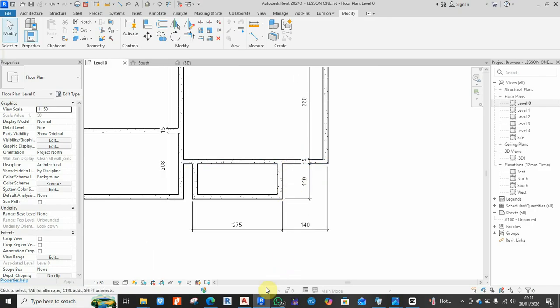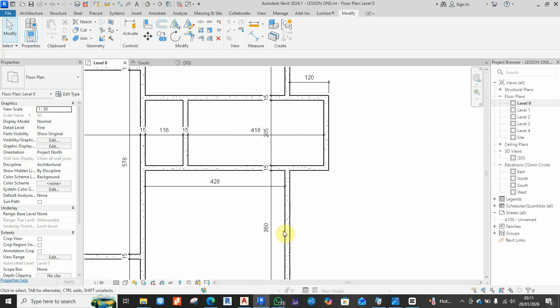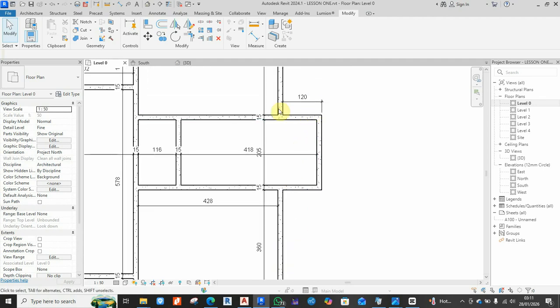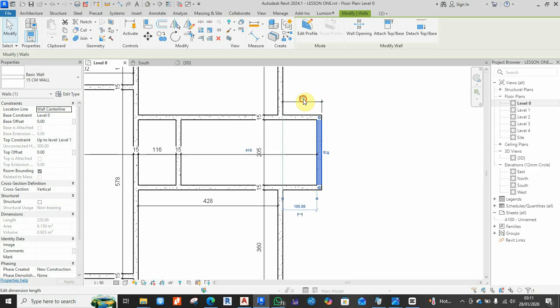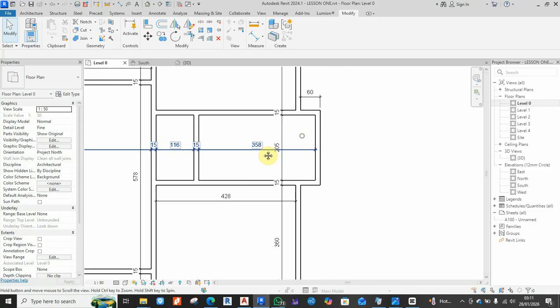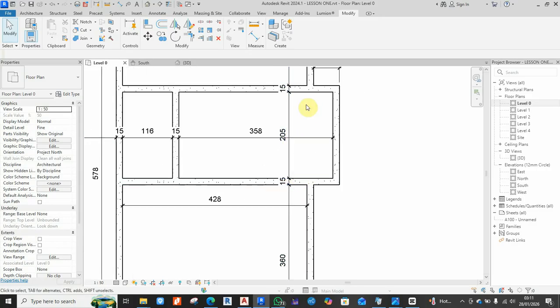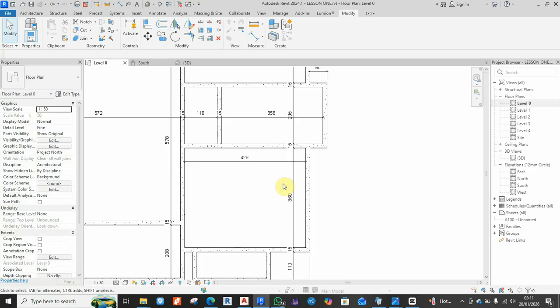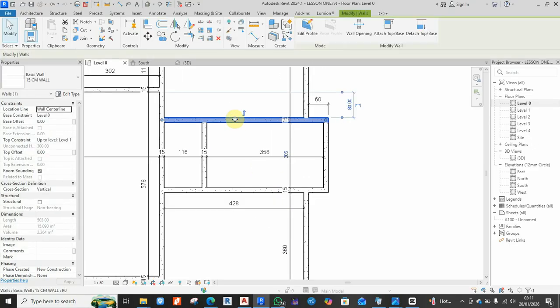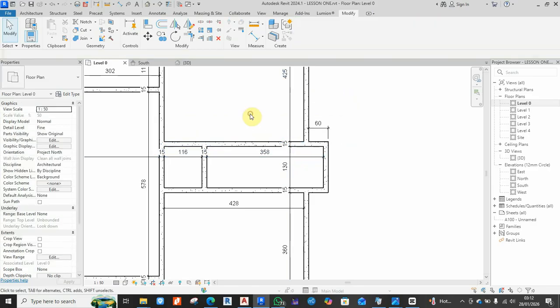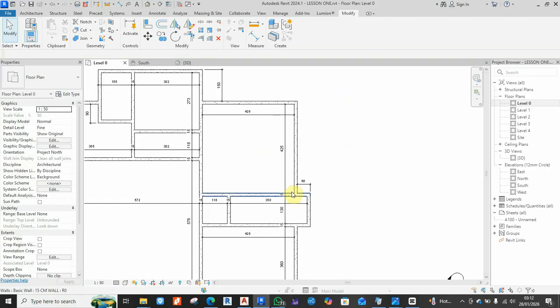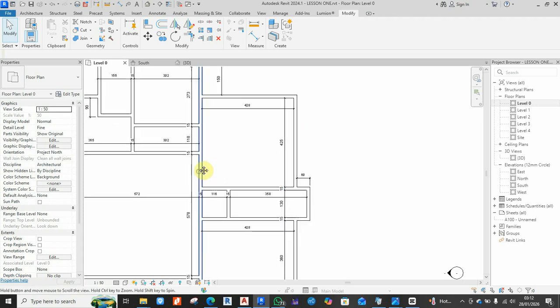This is 110 and this distance from, okay, let's just continue. First, this is 60, so I'm clicking on this and I'm giving this dimension to be 60 like this. Then next, from here to here is 130 and this distance is already okay. So I'll click on this because I want it to move downward and I'll give the dimension here 130 like this.